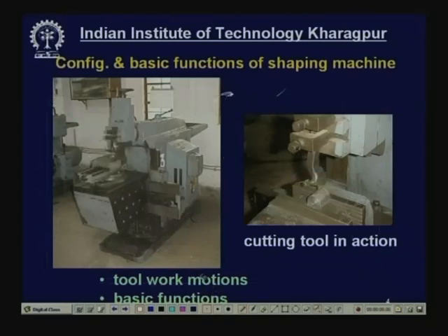Now, tool work motions. We have told the tool reciprocates, that is called cutting motion, and the workpiece is moved slowly in the transverse direction, and that is called feed motion, slow motion. What is the basic function?